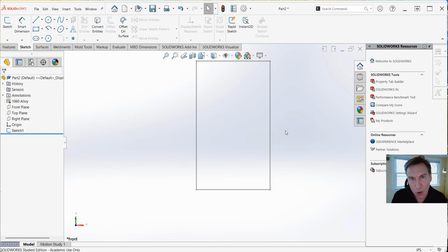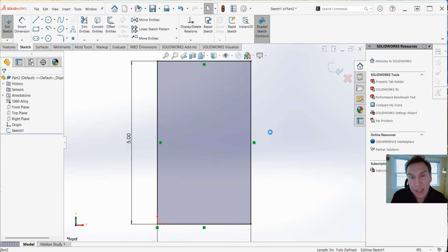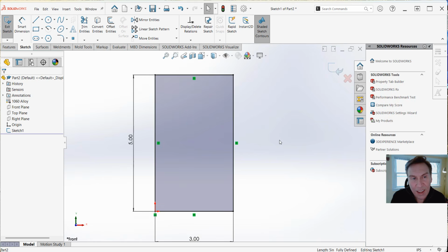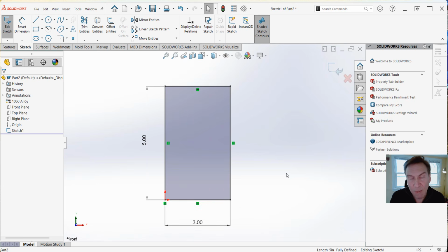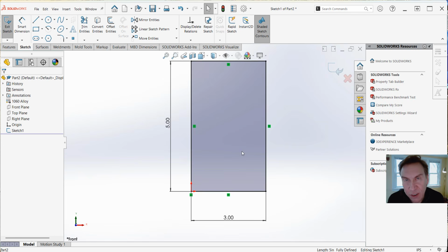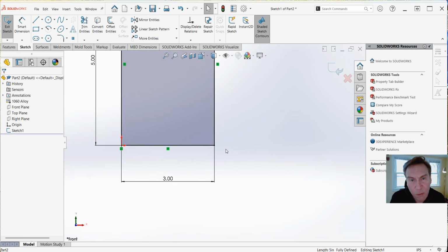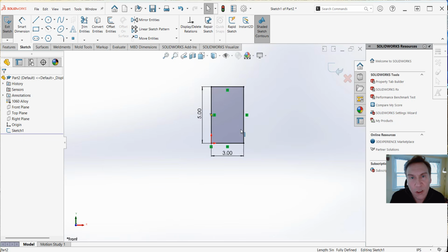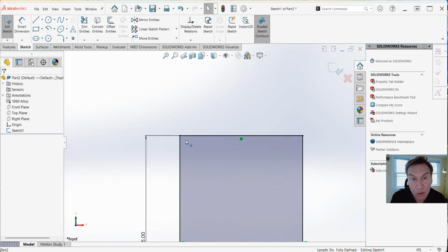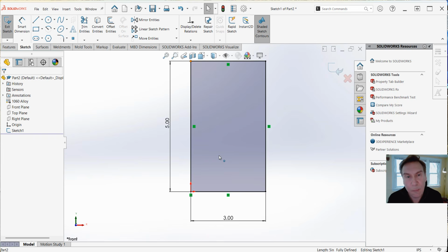To re-enter that mode of editing, you could double click. So hover your pointer over here and you're just going to double click and it will re-enter. And look at that. It actually has updated the dimensions, 5 by 3. Now, if you're wondering how, remember I said hit the F key to center it. I was also using a little trick there, which is using the scroll wheel to scroll in and out to zoom. You could zoom up the corners by focusing your pointer wherever you want it to zoom and just scroll the wheel on your mouse. Okay, and again, just hit the F key to fit it. Now, one other thing, if we're in the United States, like I said here, this should be the American National Standard.